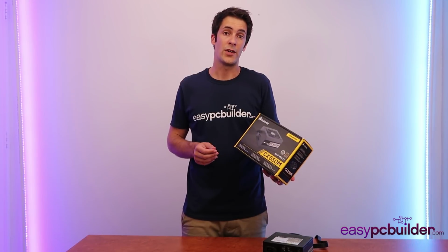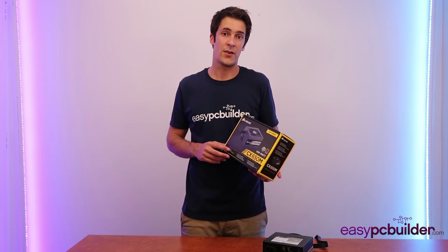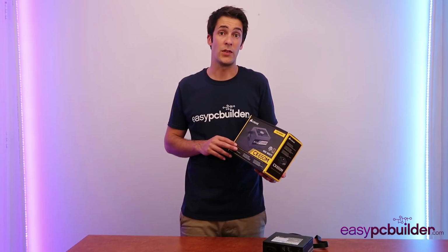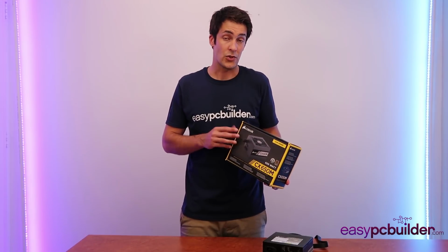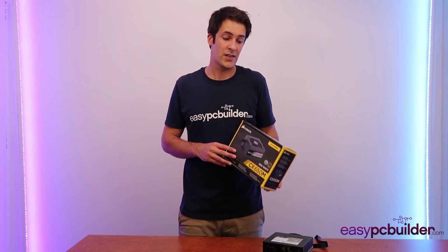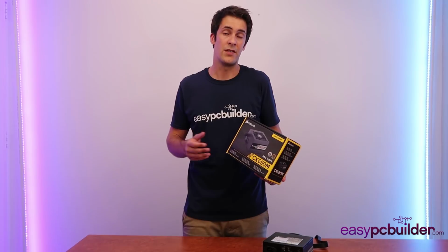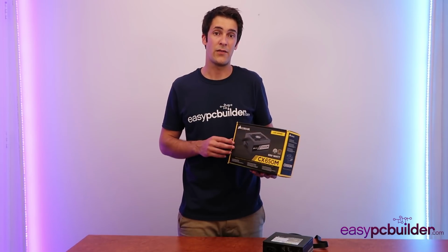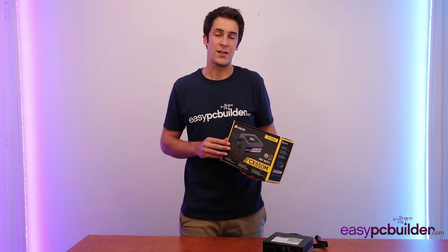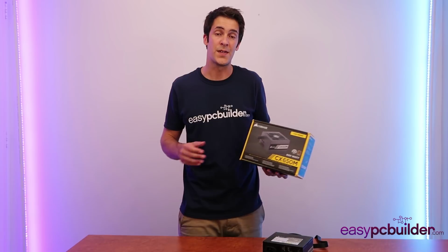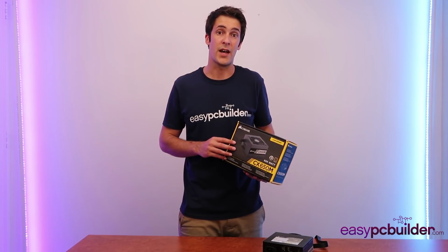So after you've decided on the wattage required of your power supply, you also need to decide on the quality and the efficiency of your power supply chosen. Generally, we recommend staying with reputable manufacturers, choosing an 80+ certification, and as well, just read the reviews online and check that the power supply that you're looking to buy has good, positive reviews over a long enough time frame. We recommend choosing a high quality power supply as it's the only thing standing between good, clean power for your computer and potential issues such as power offs and brownouts or just the computer power cycling at unknown times due to an unreliable or fluctuating power supply.